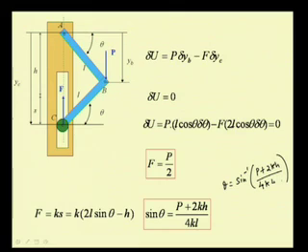So, these examples illustrated how we apply this method of virtual work to the system of ideal rigid bodies, where we neglect friction, and if there are any members that can absorb energy by elongation or compression, the same can be removed from the system and replaced by an equivalent force, and we can apply this principle of virtual work to determine the equilibrium conditions or any unknown forces that are involved.